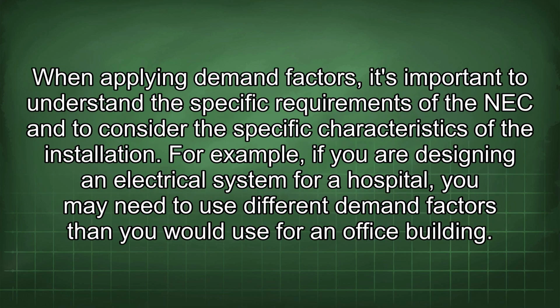When applying demand factors, it's important to understand the specific requirements of the NEC and to consider the specific characteristics of the installation. For example, if you are designing an electrical system for a hospital, you may need to use different demand factors than you would use for an office building.